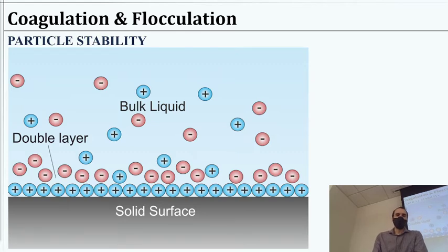So last time we were talking about the electrical double layer, or EDL, in the context of destabilizing particles, giving them a favorable environment to stick together and to essentially grow in size with a flocculation process. So coagulation would be the process of destabilizing them, maybe shrinking this electrical double layer. And then flocculation is then giving them the chance to stick together once they've been destabilized.